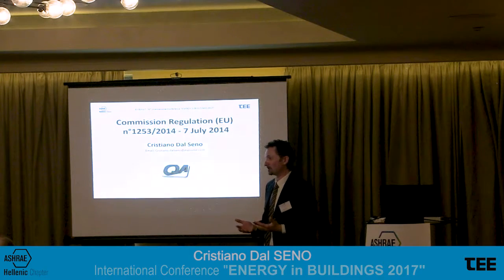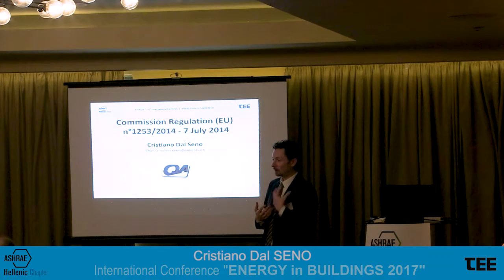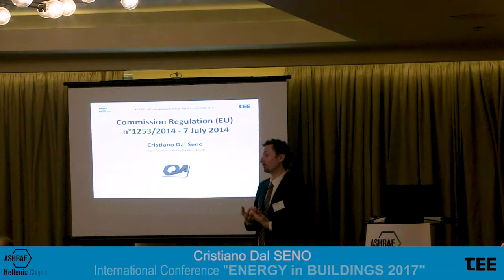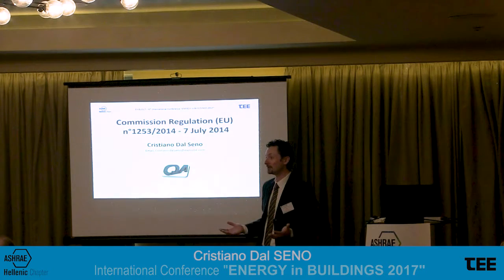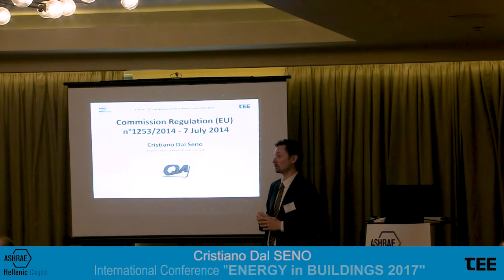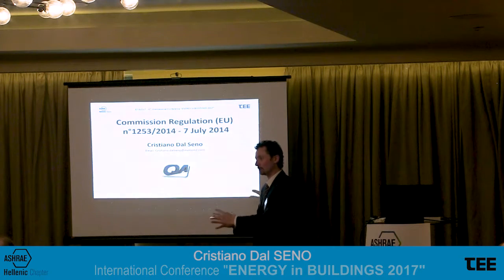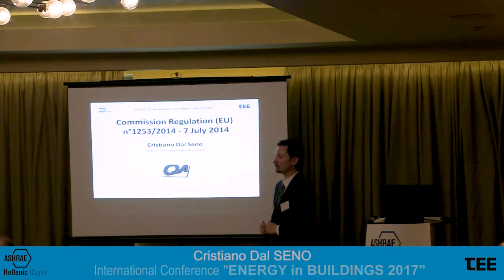It's not good, obviously, but at this point of development, the norm doesn't give suggestions in terms of what pressure drop. This is part of our job as producers and your job as consultants, because if we are making proposals for better efficiency, we must take care of the whole building and look for low pressure drop on the water side of the coil, in order to also select pumps with the correct efficiency, not using a huge amount of electrical energy and so on.